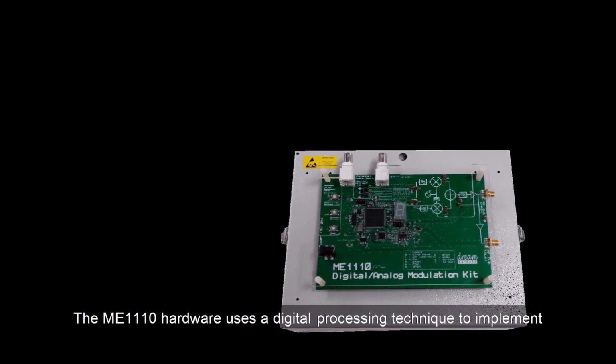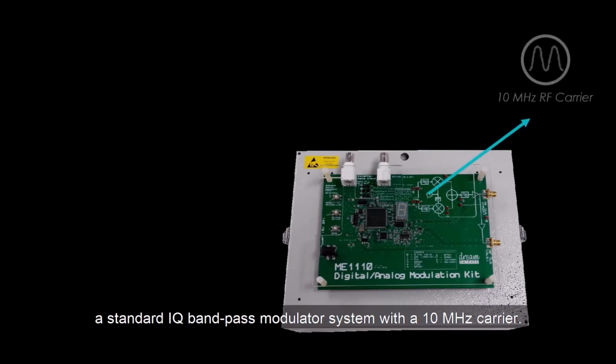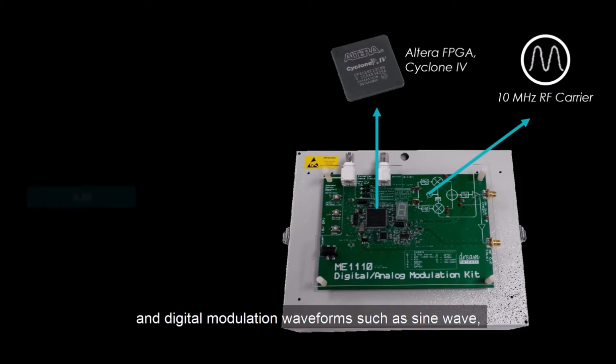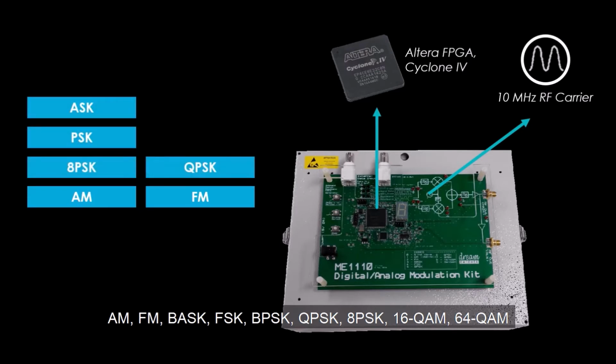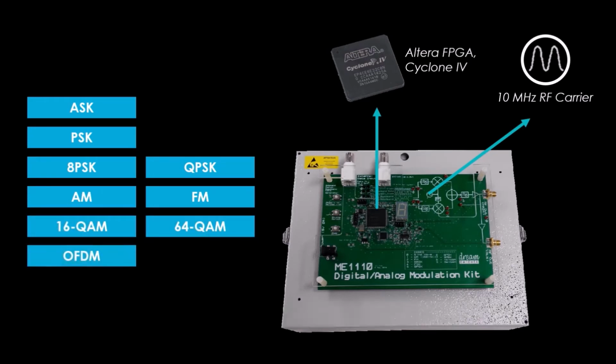The ME1110 hardware uses a digital processing technique to implement a standard IQ bandpass modulator system with a 10 MHz carrier. Using an FPGA as its core enables flexibility in generating the various digitally modulated bandpass signals. This hardware kit can produce various types of standard analog and digital modulation waveforms, such as sine wave, AM, FM, BASK, FSK, BPSK, QPSK, 8PSK, 16QAM, 64QAM, and the newly added OFDM.